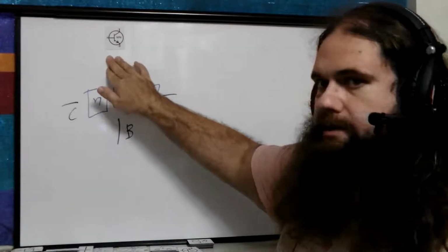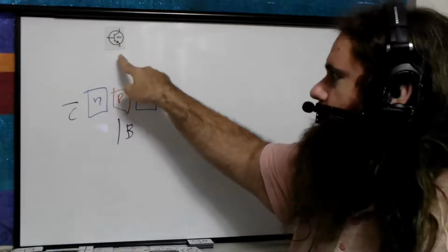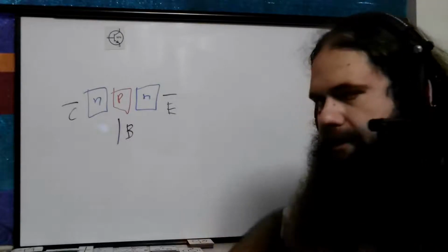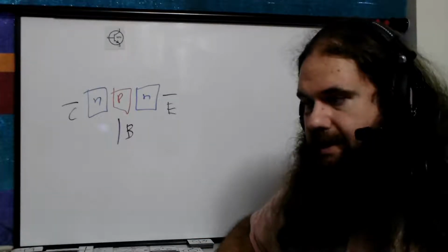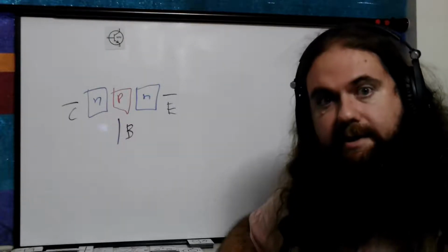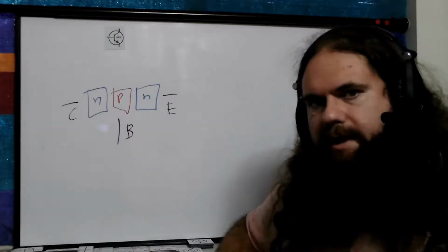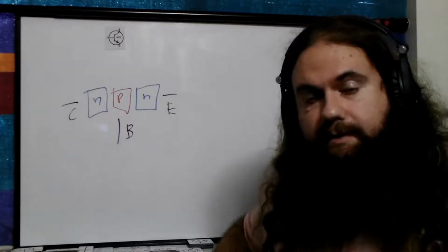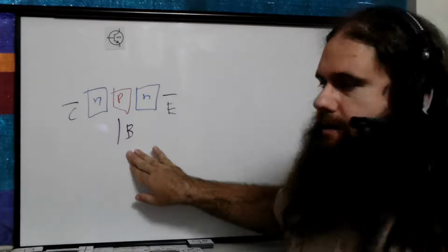So it's the base emitter junction. You might notice this little arrow. This arrow is the base emitter junction. That is the on-off switch. Why is it called the emitter? I'm not even going to bother to explain. It's supposed to be like source of electrons and sink of electrons, but then for PNP it's reversed. And also it's reversed for conventional current flow because that doesn't match electrons. So basically just memorize collector and emitter. Anything I try to do to explain is just going to make it worse. It's just like saying ground for the negative terminal of a battery. Just go with it. The point is, the base is the control.